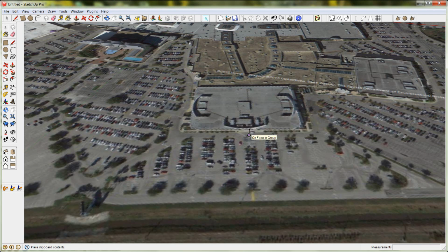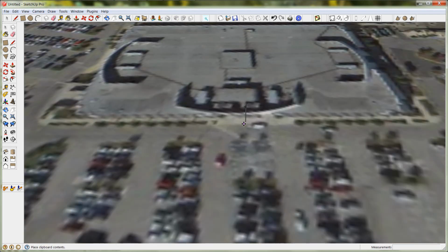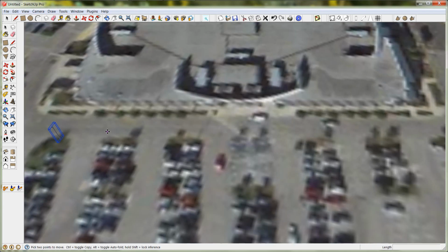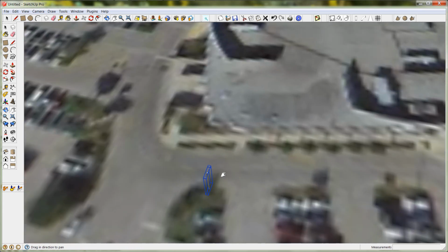And you can see the pole there, and I'm deciding where I want to put it. Maybe the best place is over here in this grassy area, or it looks like a grassy area, at the end of the parking strip. Position it in place there. Now I want to align the azimuth of the arm, so I'm going to zoom in a little bit here, grab it, and align the arms so that they're facing north and south, or I could make it east and west, whichever you prefer, but I can do that very easily. Okay, I can see that it's placed where I want it to be.